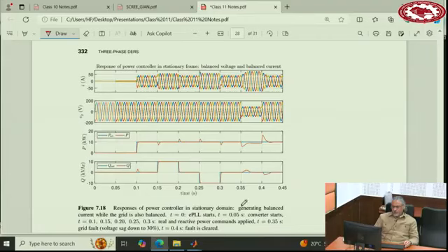In this one, obviously at the beginning is the time that the PLL is working until 50 milliseconds. And then after the PLL converges, you start the converter. There is a very soft and smooth start. And at this point, the real power set point of 10 kilowatt applies.